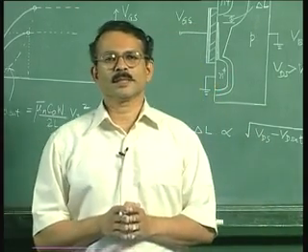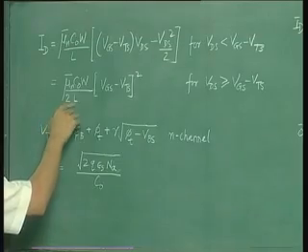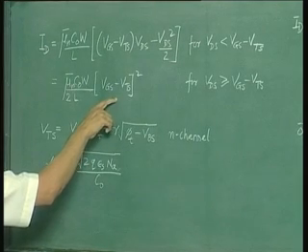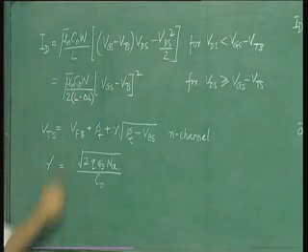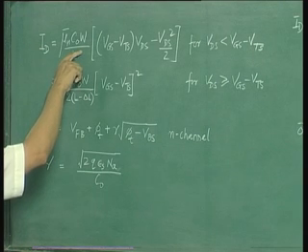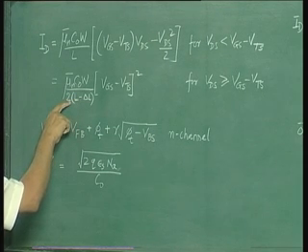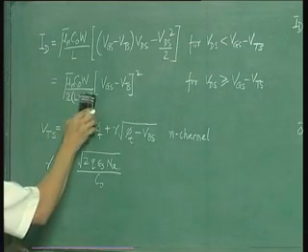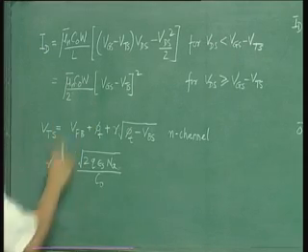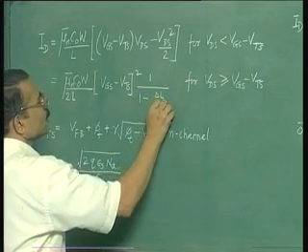Now how does this delta L affect our equations? Let us incorporate delta L and then we will have the equations as follows. In this particular equation which is valid for saturation, we should replace L by L minus delta L. This delta L does not come into picture for this equation which is below saturation. So we can now take this L out of this particular bracket, in which case the equation will get modified to L into 1 by 1 minus delta L by L.